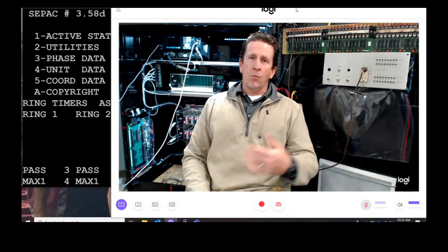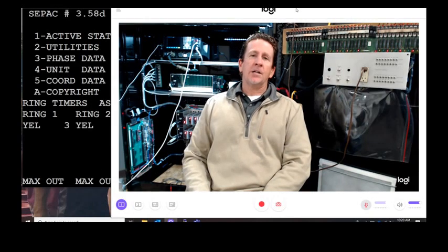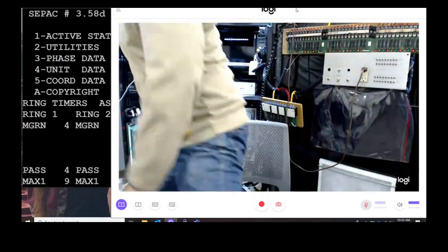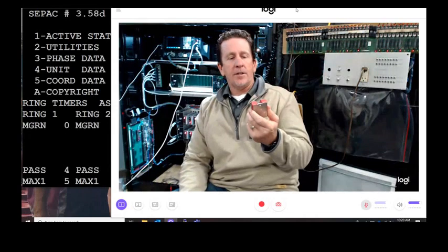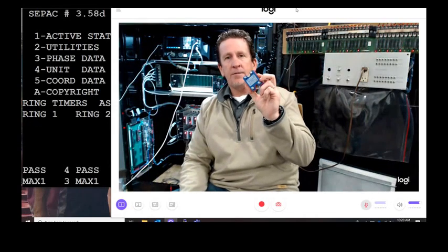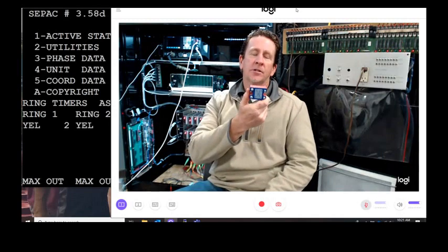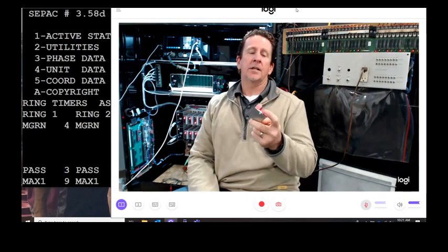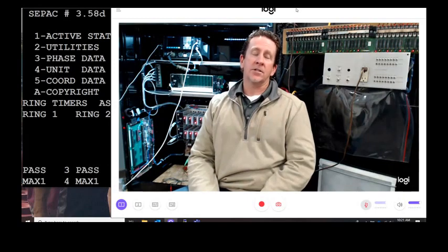So depending on what the damage was to the controller, if we've shorted out the back panel and the flasher isn't working, we have a couple of different options. Here's something that's handy to have. It's a little traffic sensor core, 25 dB, 120 volt flash cube. It's good to have a couple of these on the truck. These are ones that we have in school zone flashers. Basically, you can wire this into the cabinet, put the signals on it, it'll wig-wag, and you get the intersections to flash that way.